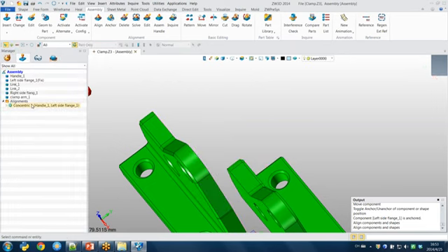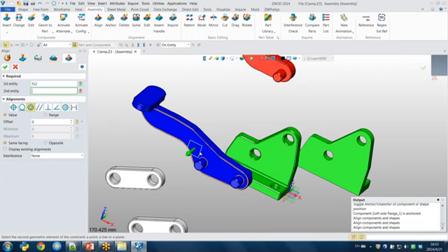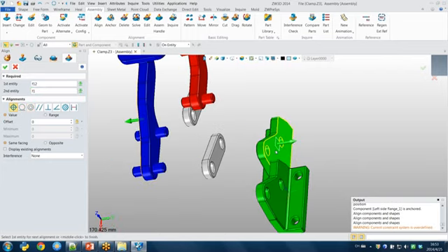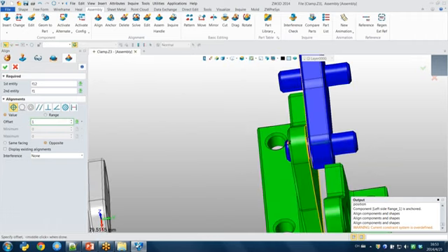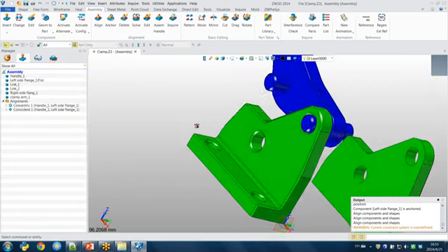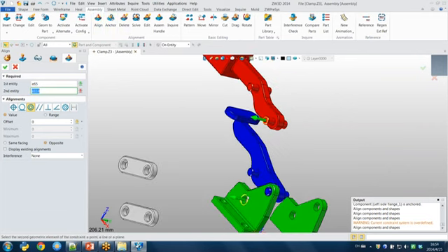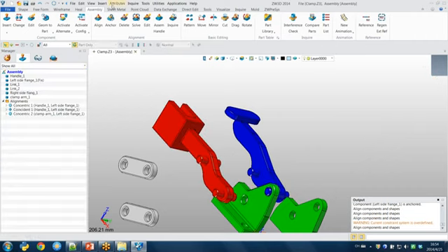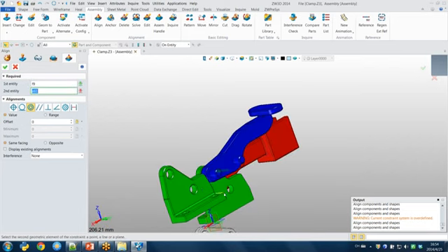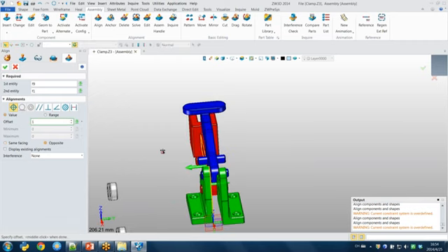Oh, I think I made a mistake. So again, do this one, same face. Surfaces, offset, give a space, press OK. Next, the same, align, same place. Okay, align, choose the surfaces, offset, give a space, press OK.